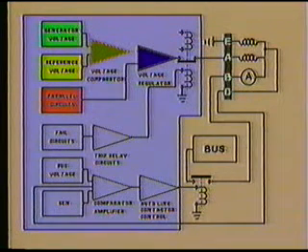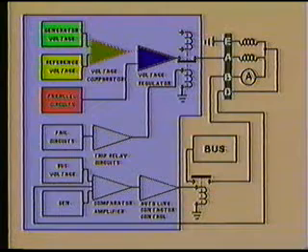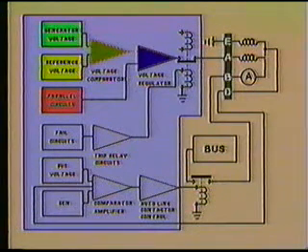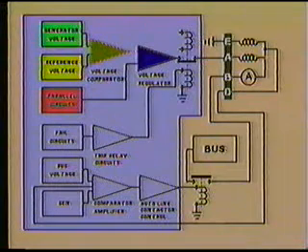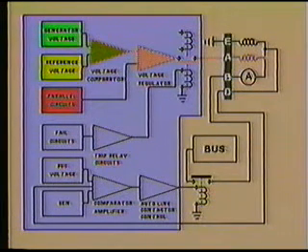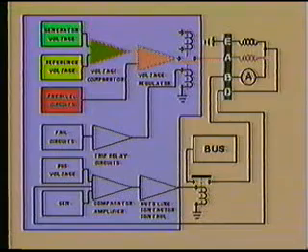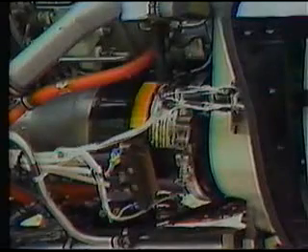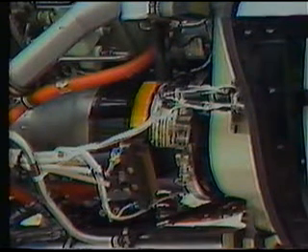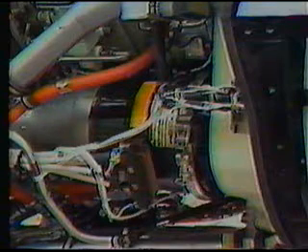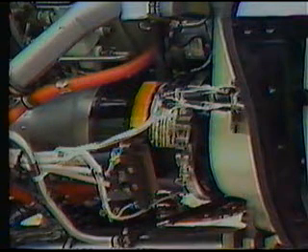The input to this stage is the output of the voltage comparator and the paralleling circuit, which is an electrical link between the two control panels. The voltage regulator will compare the outputs of the paralleling circuit and the voltage comparator circuit and determine whether the generator field current should be adjusted up or down. The voltage regulator circuit will attempt to maintain its generator's output within the proper output voltage requirements, and yet still maintain an equal load sharing with the opposite generator.